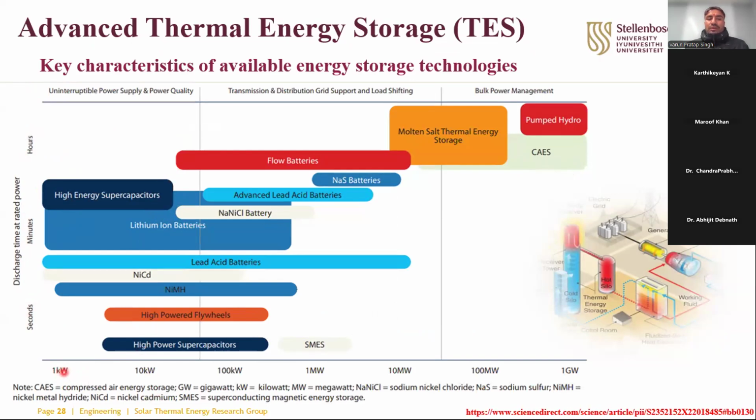At the same time, you are looking at a 1 kilowatt to megawatt or gigawatt setup. So I personally recommend this kind of table to you, which shows which fluid or media you choose for thermal energy storage, and what the transmission and distribution cost is, what the operational cost rate is, and what the installation cost of that kind of setup is. And you can see even lithium ion battery is already surpassed by molten salt technology.